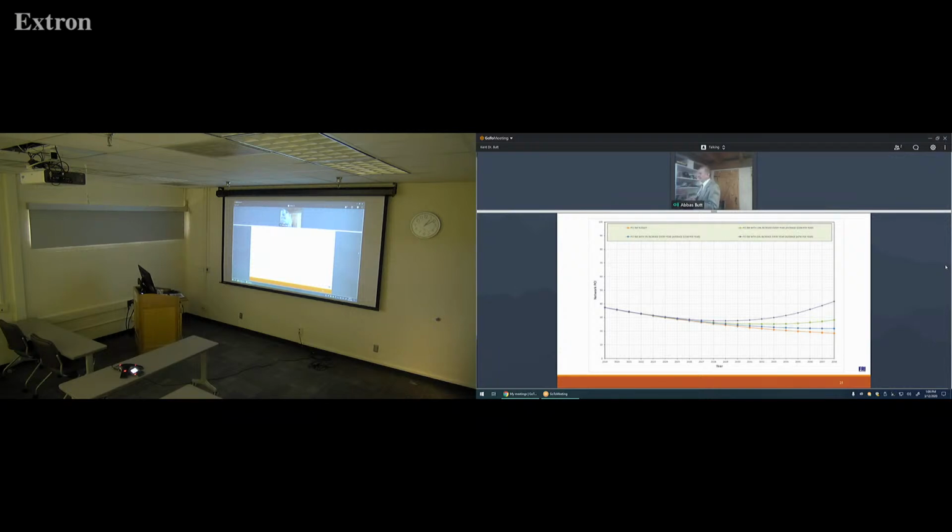And therefore we are showing here that you need at least a 10% increase even to reverse the rate of deterioration, which is the green curve. But then if we increase 15%, that is a sharp change in the reversal of the pavement deterioration.